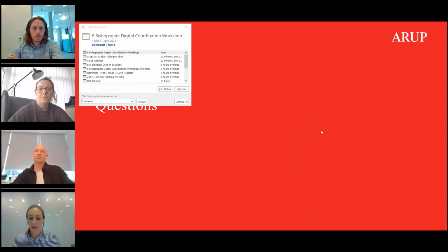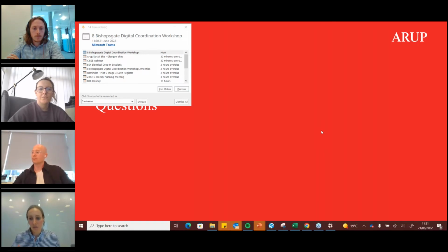Otherwise, I would start by looking at, as you would do for any project, what the peak loads would be, so identify what the loads are, identify if there are any constraints on what temperatures for distribution you might have, depending on whether it's retrofit or whether you need particular emitters to be used for the application. And then if there are any client resilience requirements.